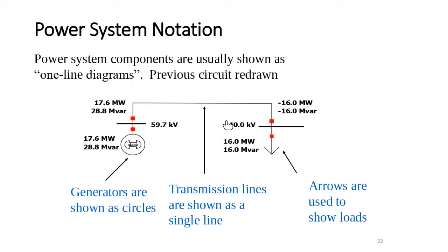I'm talking about this circuit here, and we call it a one line or single line diagram. Remember, when you draw a single line diagram, it means you draw just one line like this, but it represents three phases.